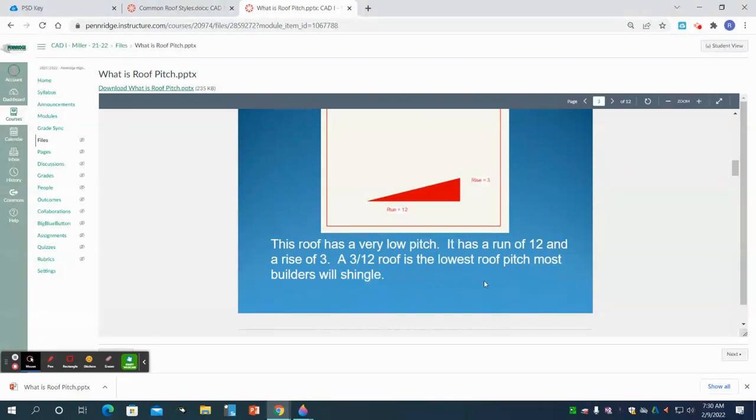If you have shingles or cedar shake roofing, they'd want the roof to be at least a 3/12 or steeper to put shingles on it so that the moisture is running off the roof. Now, if somebody's going to have a shed roof with a pitch of 1/12, we can put a seamed metal roof on it, and that'll be fine. So we can do a real low-pitched roof on this project if you want to.